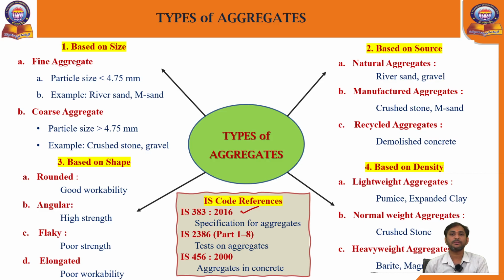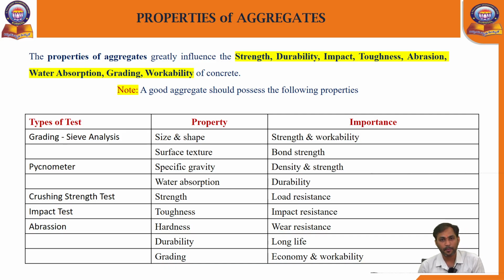And for construction purposes, what type of aggregate? Nothing but 20 mm size or 40 mm size. For that, a good grading process will be available, whether it is poorly graded, uniform graded or well graded. Poorly graded is also called gap graded. Those aggregates will be used in concrete. Next, zones: zone 1, zone 2, zone 3, zone 4. These conditions are applicable in IS 456:2000.